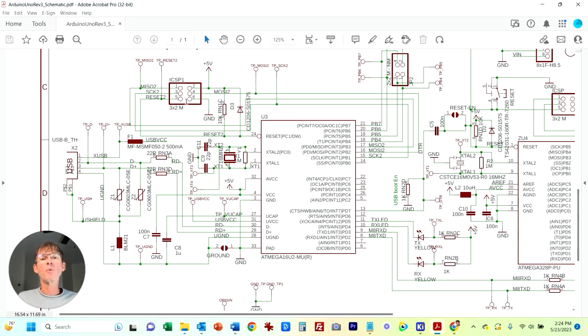There are lots of names for it, but it's basically a piece of hardware that converts from USB on your computer to the serial programming protocol used for that specific microcontroller. Different microcontrollers have different programming standards, so the programmer needed will typically be unique to the microcontroller, or at least that family of microcontroller.